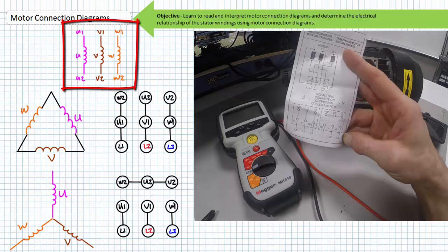In this case, the motor has 3 coils, U, V, and W, and each coil has 2 ends, U1 and U2, V1 and V2, and W1 and W2. The terminal block is arranged quite cunningly in that a set of 2 jumpers can be used to connect the motor in either a Y or delta configuration.